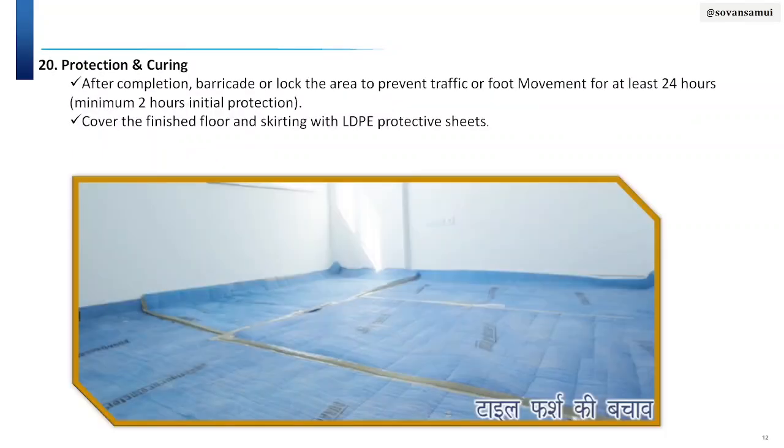Okay. Next point is protection and curing. After completing all the work, you should always protect the tiles with an LDPE protective sheet, or barricade the area to prevent foot movement or any kind of traffic for at least 24 hours.